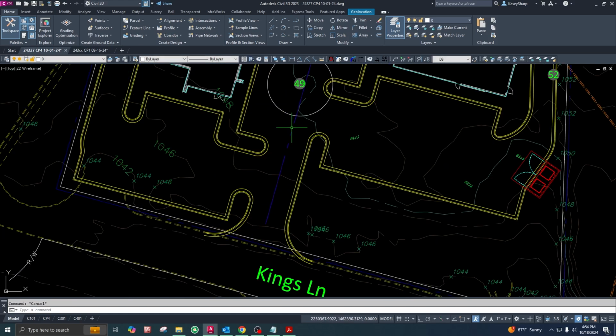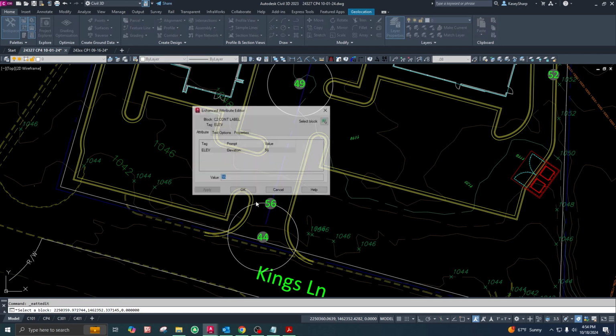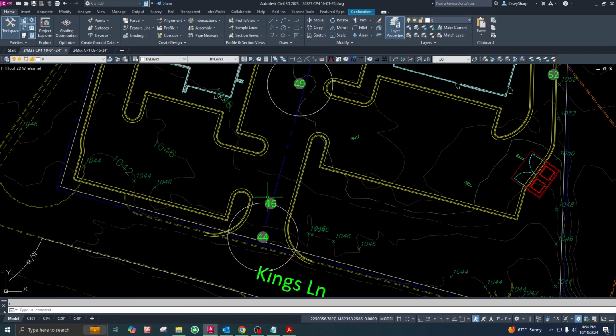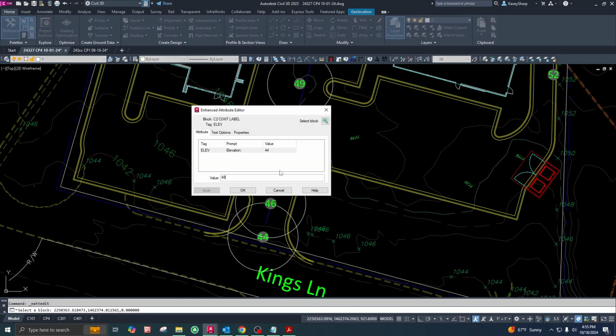and then we're going to have, what are we at right here? 1044. So here's our 44. Okay, and then if we did about a 10% slope, it'd be 2 feet over 20. So we have a 20 foot radius circle, and then our 46 would be about here. Excuse me, 46. Another 20 footer. Be 48 there.